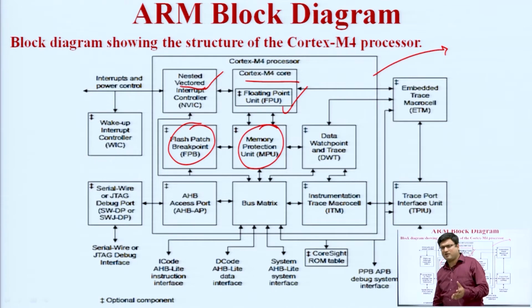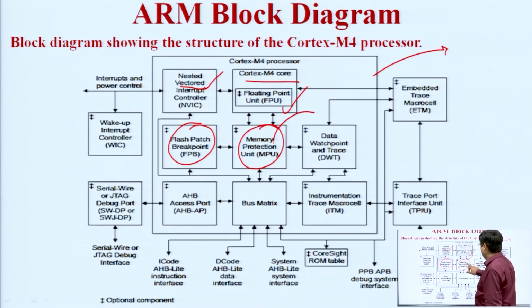How the IP library is executed in the SoC chip, whether it is in RAM, ROM or flash, is managed by the memory protection unit. It has a watchpoint and trace point unit. It has an access port. Access can take place through this unit.